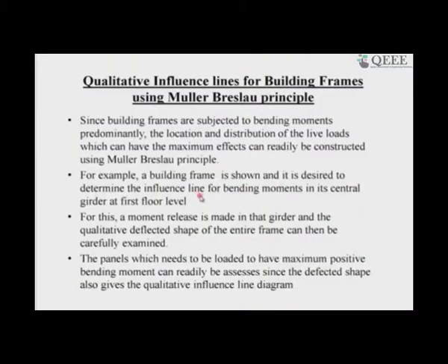In your slide, we will demonstrate how useful the Muller-Breslau principle is to draw the qualitative influence line for building frames. Since building frames are subjected to bending moments predominantly, the location and distribution of the live loads which can have the maximum effects can readily be constructed using the Muller-Breslau principle.